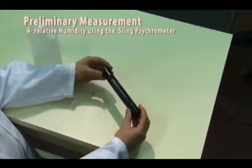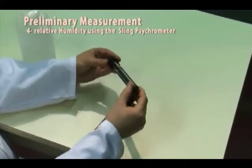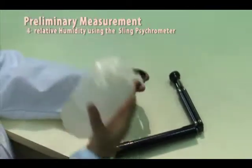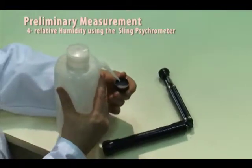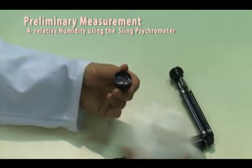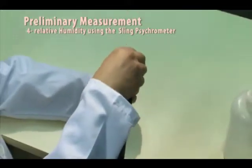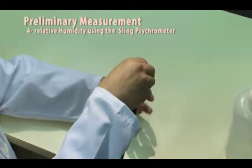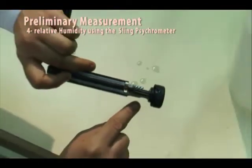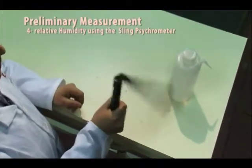As a part of the preliminary measurements, relative air humidity can be measured by using the hygrometer or the sling psychrometer and the psychrometric chart. The sling psychrometer consists of two thermometers mounted together with a handle. The other has a cloth wick over its bulb attached to a water container and is called a wet bulb thermometer. When a reading is to be taken, the water container should be filled with distilled water.